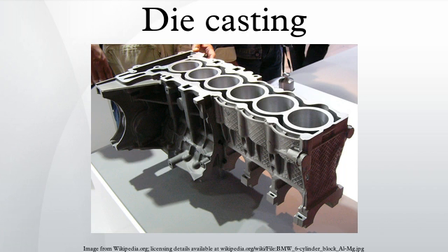Die castings are characterized by a very good surface finish and dimensional consistency. Two variants are pore-free die casting, which is used to eliminate gas porosity defects, and direct injection die casting, which is used with zinc castings to reduce scrap and increase yield.